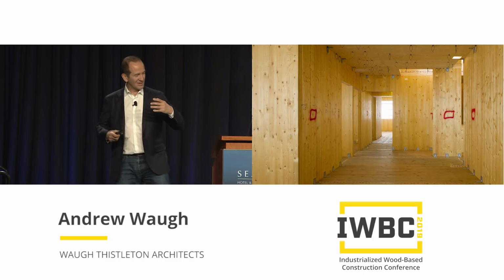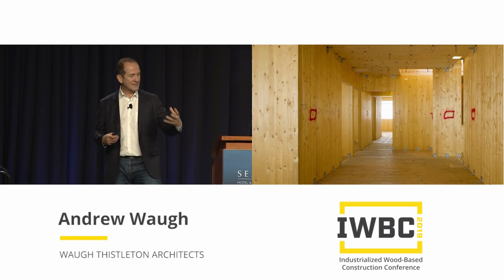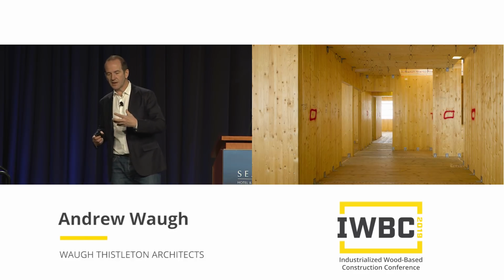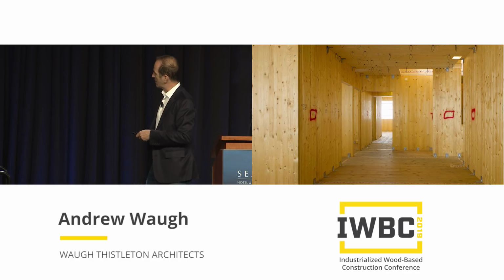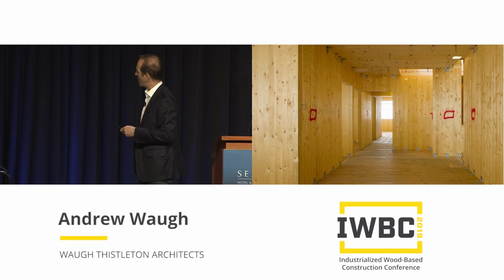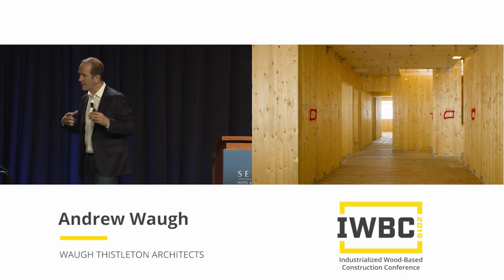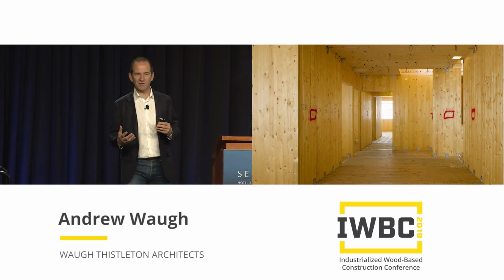But we've come a long way since then, but still understanding a lot of the simplicity of the details of this building, I think are actually essential in moving a technology forward. So you can see the whole building's put together with a 3-inch galvanized shelf bracket and a 5-inch screw, and then the electrics go in here on a plastic tie, and the whole thing, incredibly simple, incredibly straightforward.